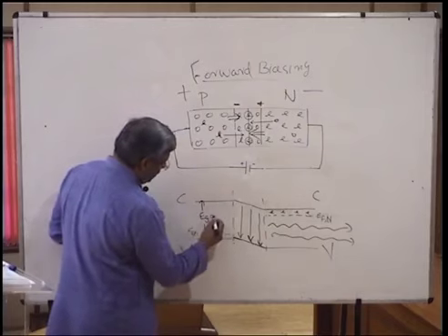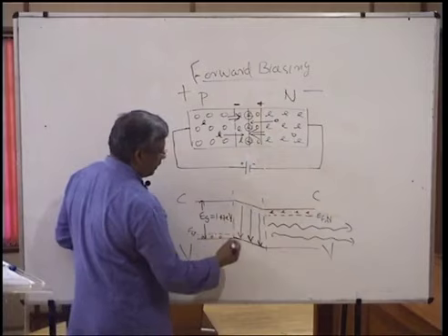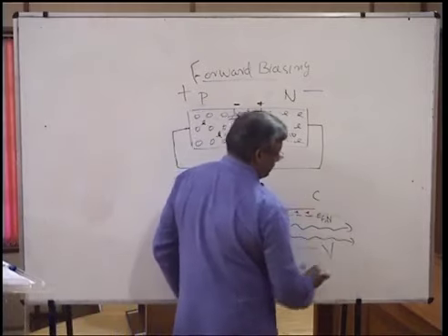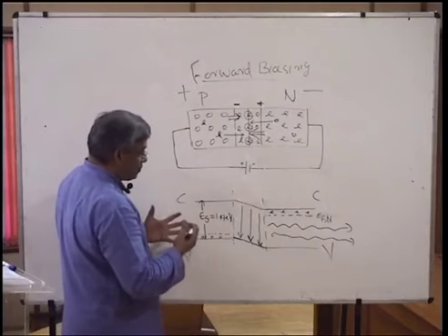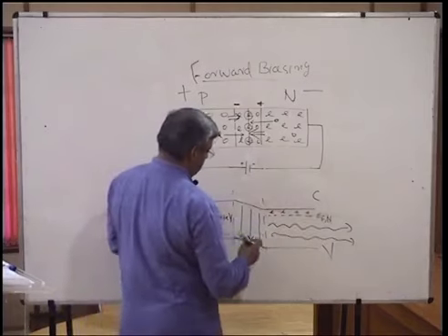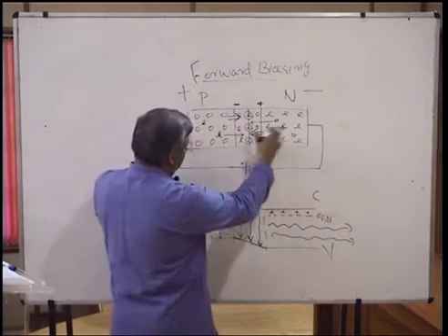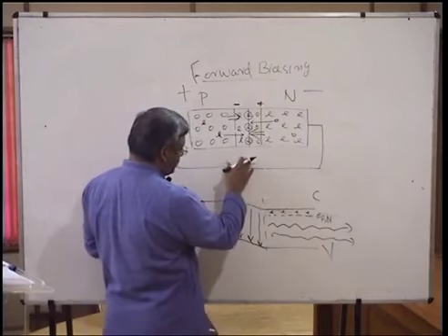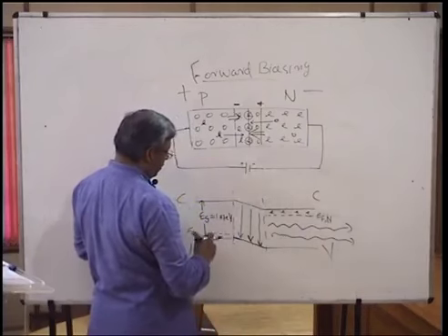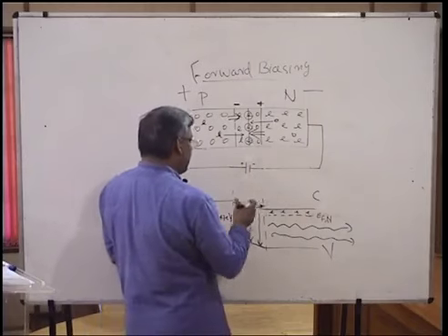Now, if it is around 1.47 or so electron volt, the corresponding light will be red light. So, a red LED you will get. So, this is what is called LED, light emitting diode. So, you have a diode here, a PN junction diode, and now you are giving a forward bias to that PN junction diode, and forward biasing of a PN junction diode will lead to the recombination of